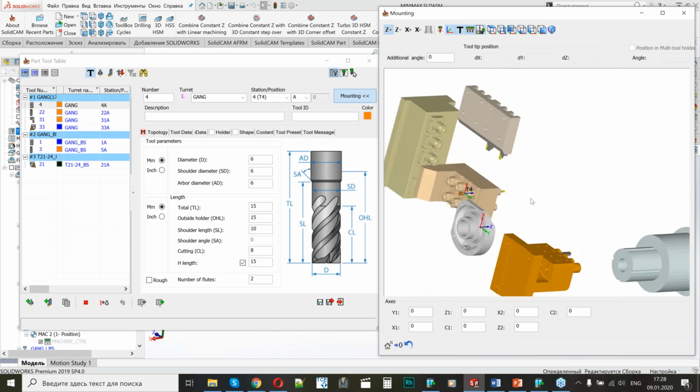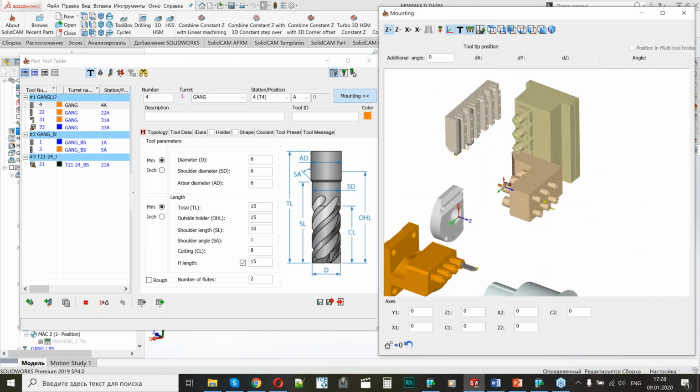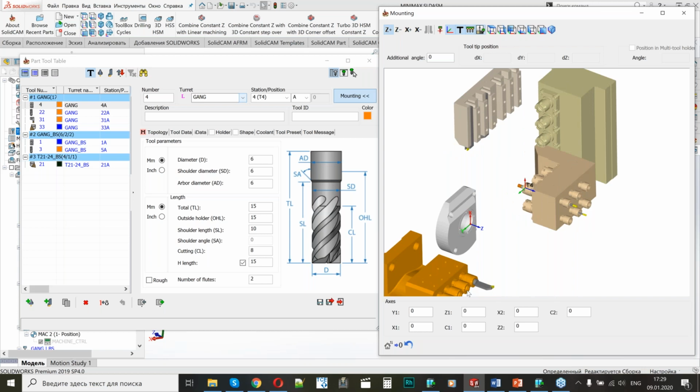So you have a lot of different combinations of tools inside all Swiss type machines, and you can divide all tool blocks and create as many turrets as many blocks you have, or you can divide tools according to drive units or according to axis distribution. For this particular machine, I created three turrets, three tool blocks. So I divided all the tools I have here into 3 blocks, because 3 submachines is a minimum number for this machine. I will explain what I mean.